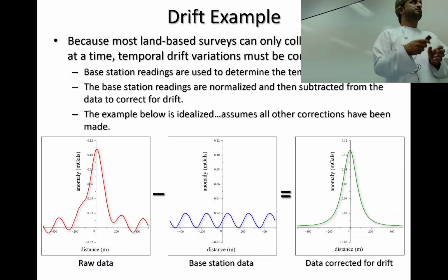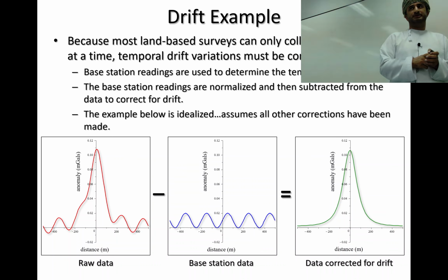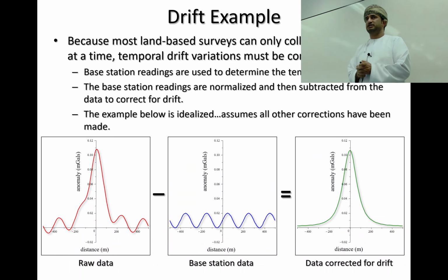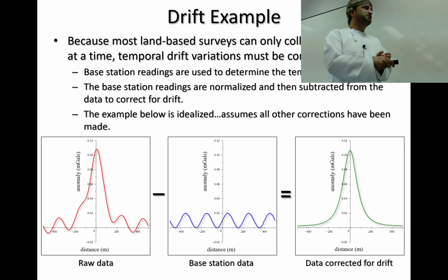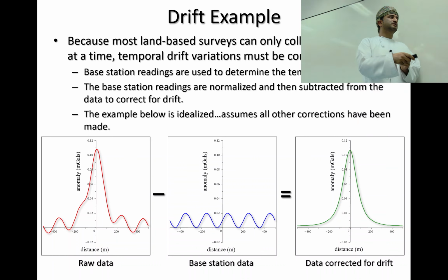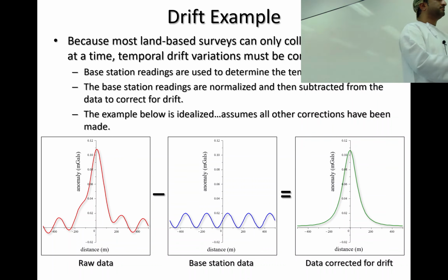I go and repeat the measurement at the base station, the station I take as a reference point. If I assume that I removed every other parameter, this is the change due to time. The overall recording includes time change and some geologic change at many readings. Whereas in the base station, I see a repeating change throughout the day.